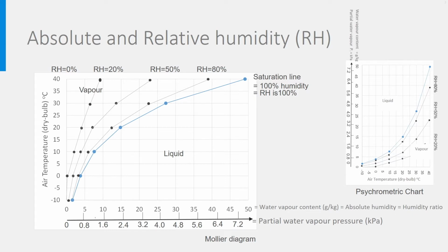Let's look now at the complete Mollier diagram and all its parameters with a focus on the equations used for absolute and relative humidity. A diagram is easy to use, but equations may be needed for more accurate calculations, especially at pressures different from the atmospheric one at sea level. The graphics we used in this course are for the air pressure at sea level.